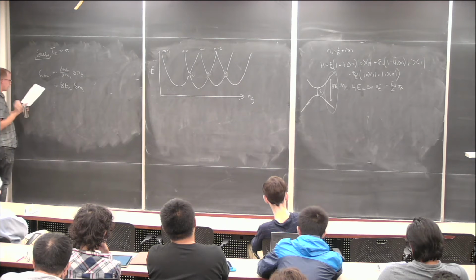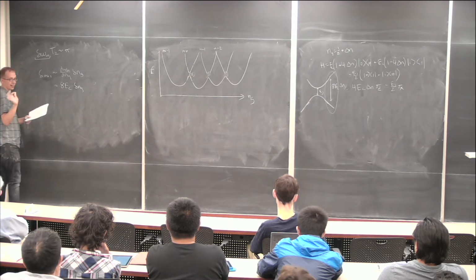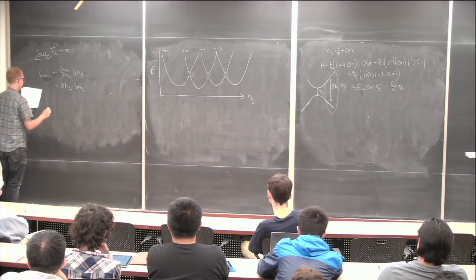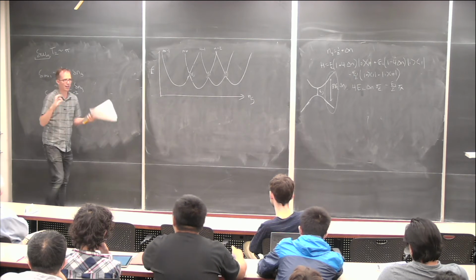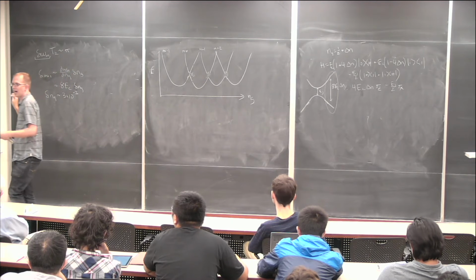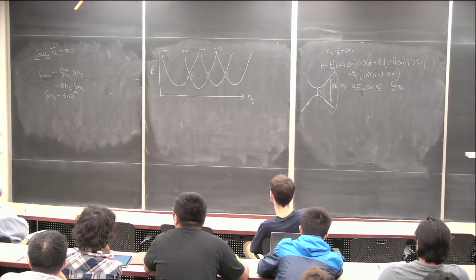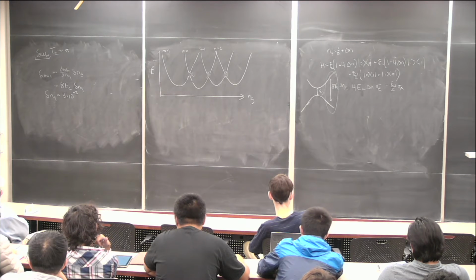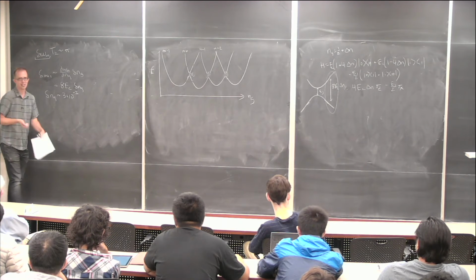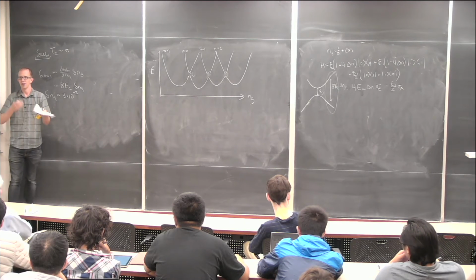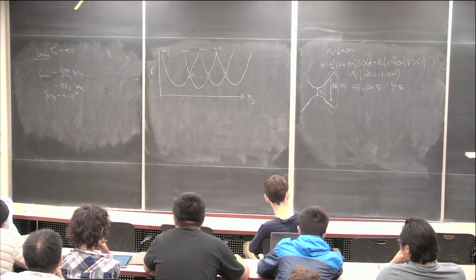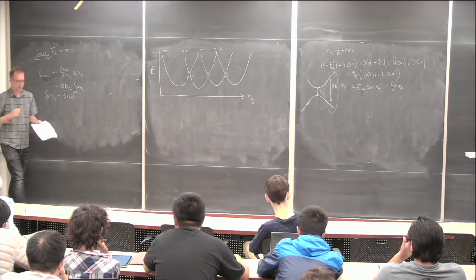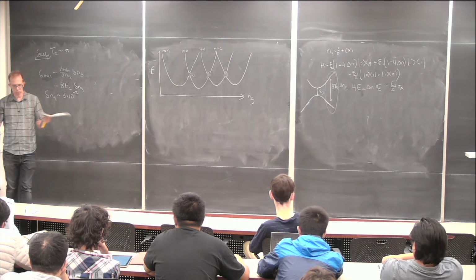And we know empirically that delta Ng is approximately 3 times 10 to the minus 3, at around 10 hertz. This number is a typical value that we measure when we make one of these circuits. It appears to be quasi-universal in that we don't really know exactly what's causing it, some sort of two-level fluctuators on the chip, but when you measure these with different fab processes, regardless of where you are and regardless of the details of your circuit, you're going to get a number that's in this ballpark, roughly speaking.